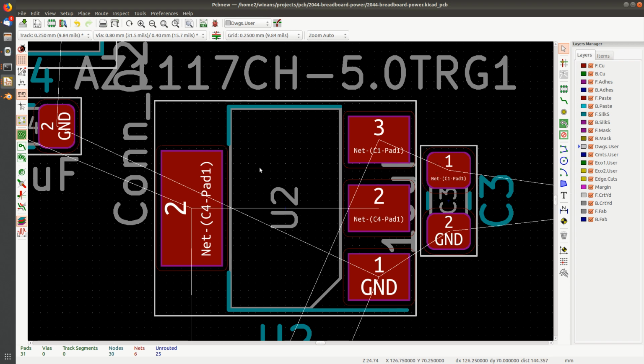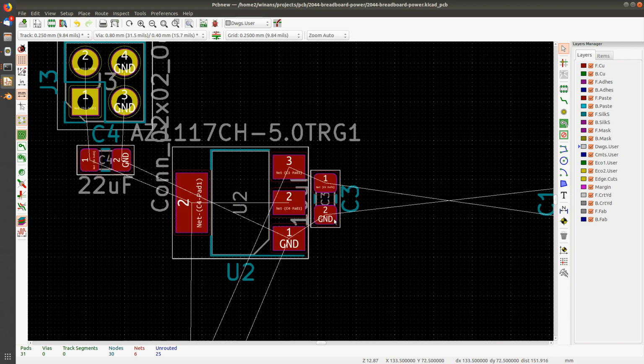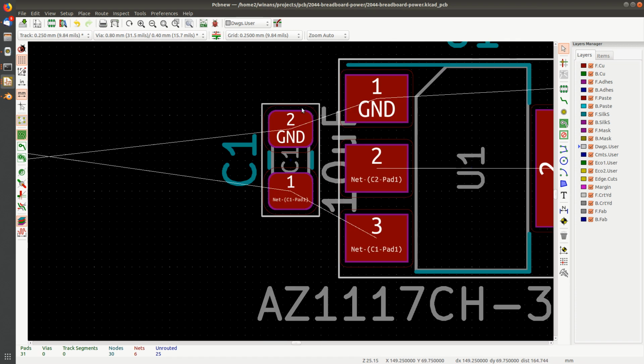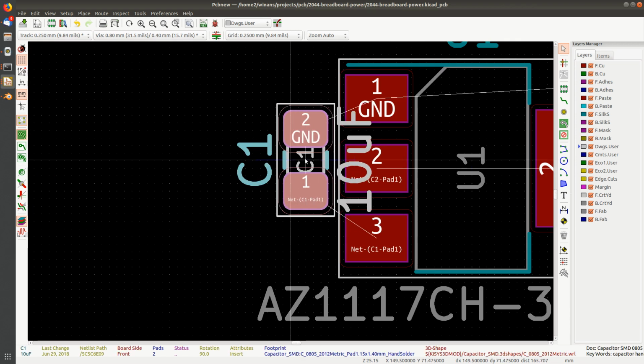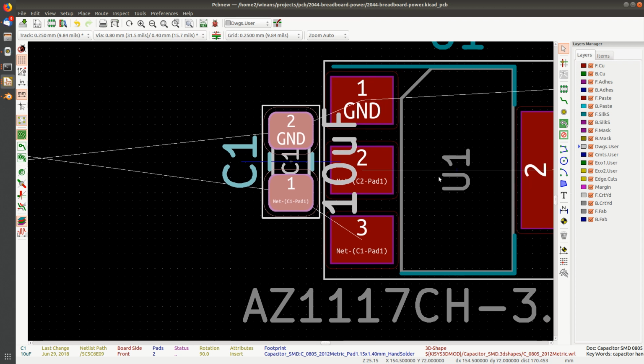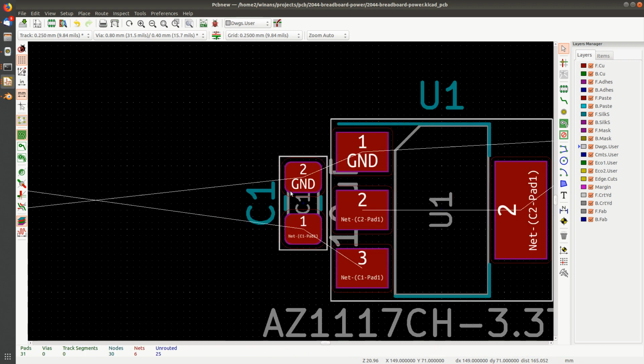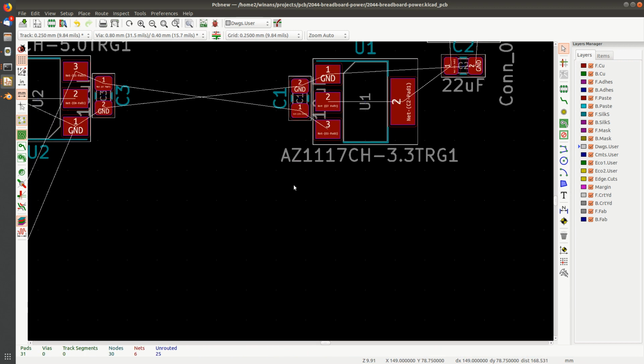All right? So they give you these as a bit of a reference and say, you want to avoid getting any closer than that. So I'm going to go ahead and put it up really close because I happen to know that when you put this regulator on here, the pins sit right in this area. And you have plenty of room, in other words, to get your soldering iron in there. It's really not a problem.